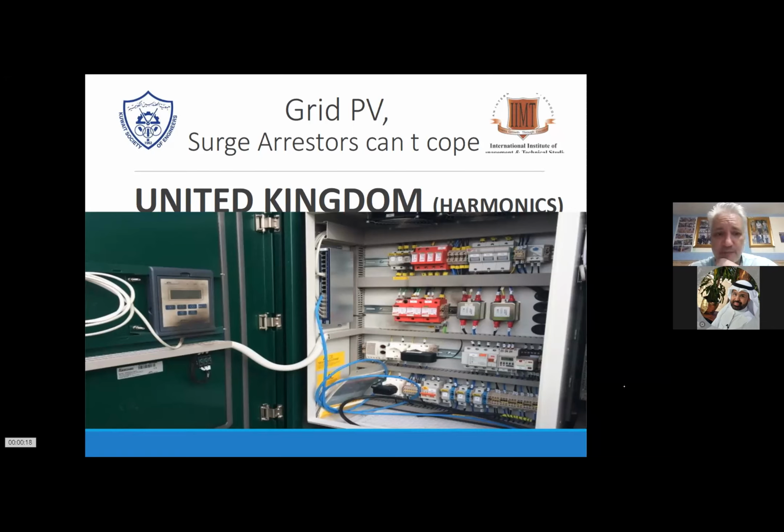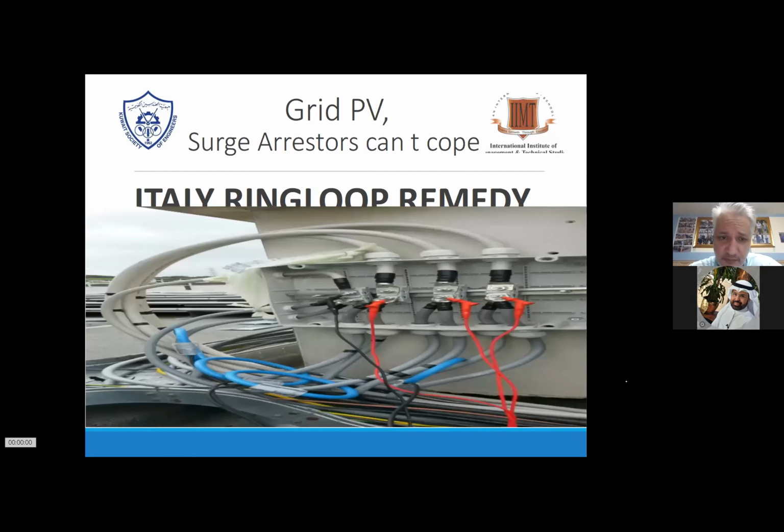So that is an issue. Sometimes DC cables lie in parallel to the high voltage or medium voltage cables, or there's another source that is crossing your PV field. That's a problem, because you're picking up noise from other cables.